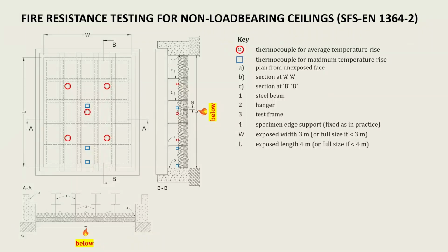This is an example of fire resistance testing of a self-supporting ceiling exposed to fire from below. Resistance to fire testing is applicable to different types of ceilings, which are either suspended by hangers, fixed directly to a supporting frame or construction, and self-supporting ceilings. Within the test method, the ceiling can be exposed to fire from below the ceiling or above the ceiling to simulate fire within the cavity above the ceiling. Note that a test result is not applicable to other ceiling types or fire exposure directions.